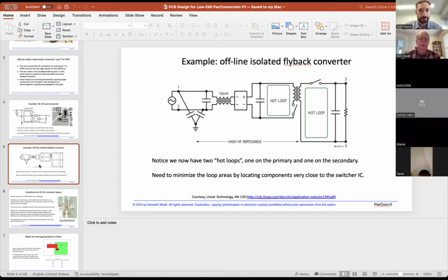You've got the aircraft body, and an antenna of a certain length and location, and you can simulate couplings from the antenna to maybe other antennas. But to simulate the performance of a product for EMC, I don't think we're there yet. I'm not sure we'll ever get there.